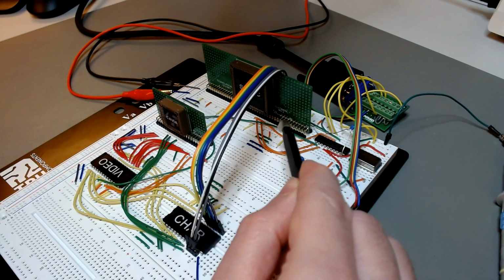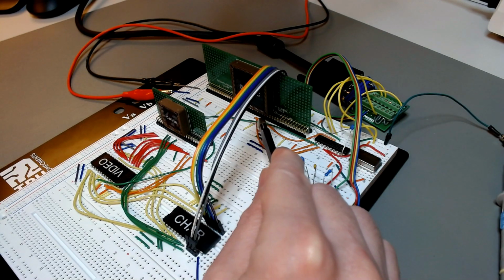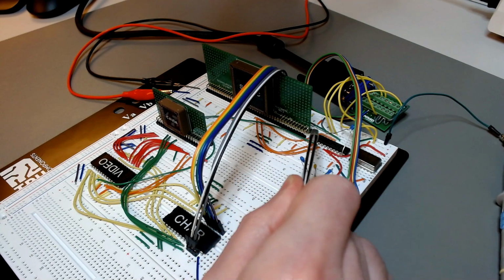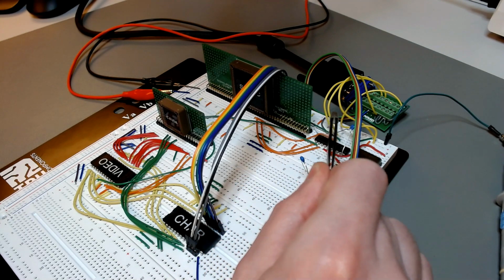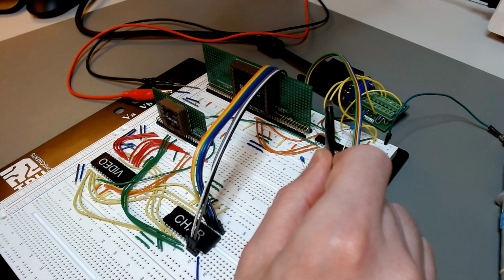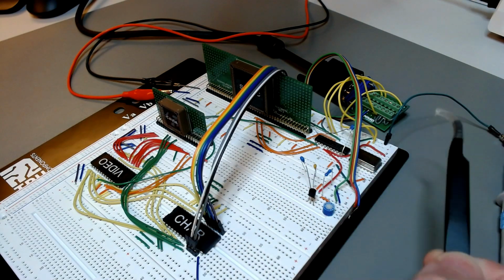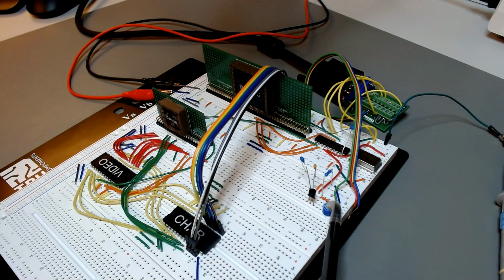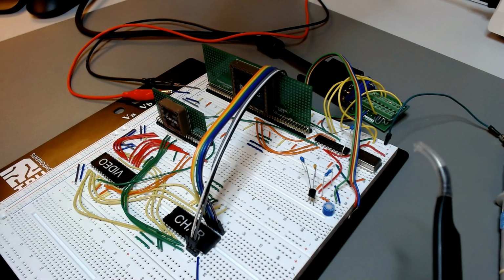Now the vertical and horizontal sync pulses are in these two orange wires. They come in here, they are also buffered, and then they go out through these yellow wires there to the VGA cable. There is also a little potentiometer here which allows us to adjust the brightness of the image, and that pretty much completes it.